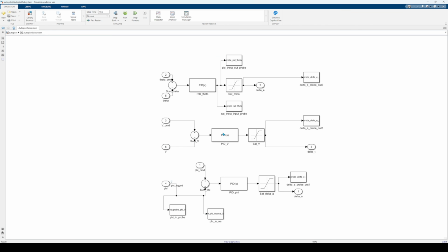And inside, 3 cascaded PID controllers: the bank hold, the pitch hold, and the airspeed hold. Each one takes a command set point, subtracts the current value, runs a PID, and saturates to the control surface envelope. Just standard cascade autopilot architecture.